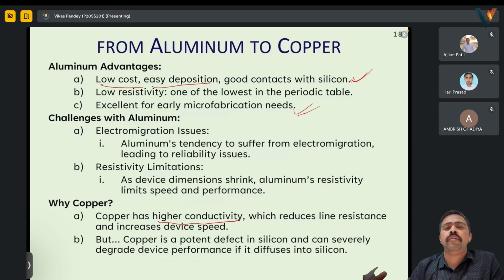So this is common for copper-based electrodes. They are used in the process. Then when we're talking about metal deposition, one thing we have to take care of is the sticking coefficient. That is, what is the probability that an incoming ion will stick to the surface where it deposits. Okay.